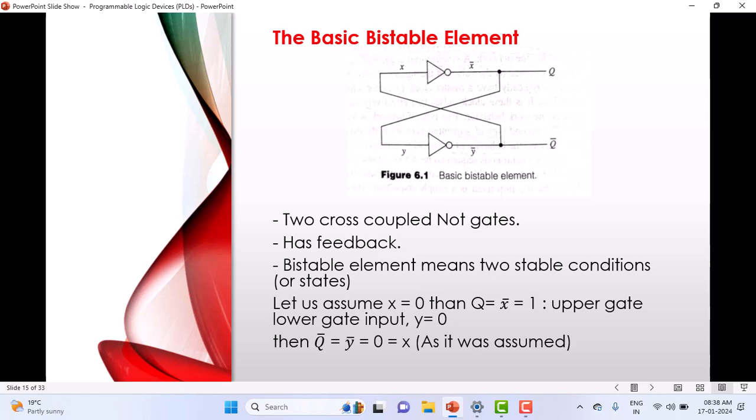Look at the transistors inside this. How do you construct inverters based on transistors? Have you seen the internal circuit of an inverter? It's made up of two transistors. If you prefer BJT, with the help of one transistor and one resistor, you can make an inverter. Look at it from a circuit point of view.